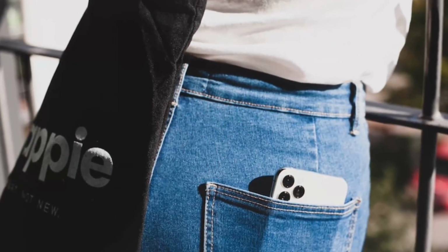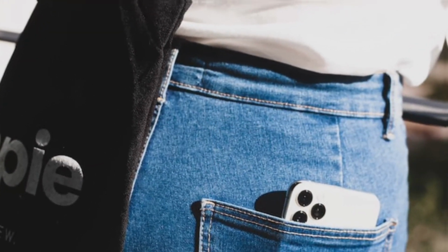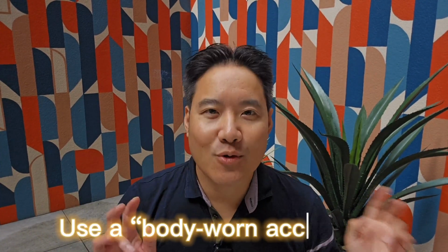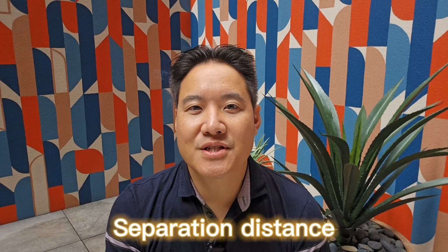But in any case, if you ever read your user's manual, every manufacturer warns the end user of the potential danger of using it too close to your body when you're in a constant transmitting mode like a voice or video call. And the manual warns the end user to use a body-worn accessory in a separation distance from the body in these scenarios. Not to say it'll always fail the SAR limits in that condition, but it's just saying putting a gap with a belt clip between you and the back of the device will guarantee it will never exceed the federal limits for the torso at that separation distance.